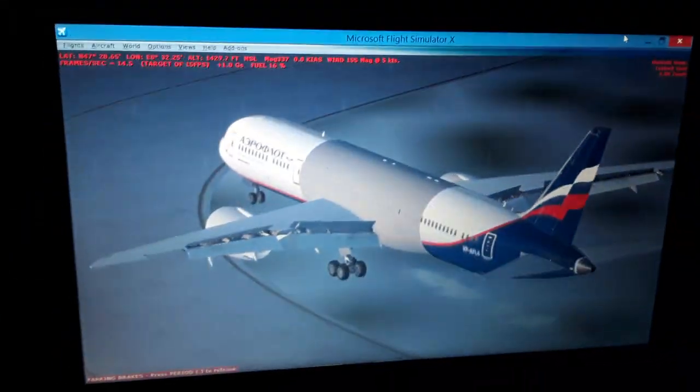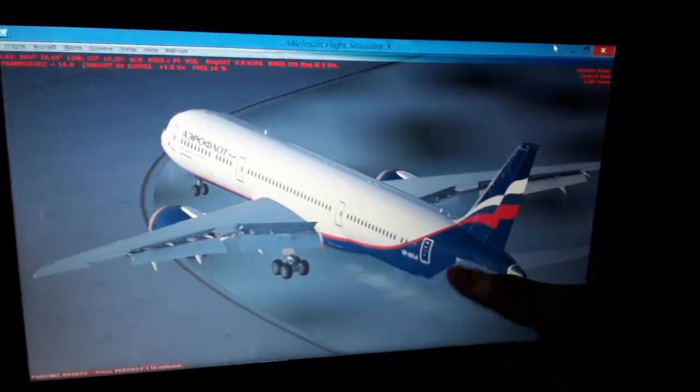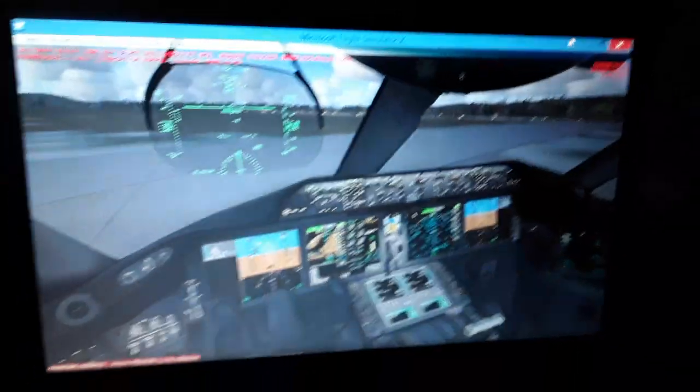It also calculates the mean aerodynamic chord position of the forward wings, which is 23% for this flight. The mean aerodynamic chord of the forward wings is the position where the maximum aerodynamic lift occurs. In the forward wings it is also the position where the stall will begin, when the airflow becomes detached from the top surface of the wings as we fly. So you will see that also. I will show you some of the aerodynamics of the aircraft, the wings, the flight controls, Newton's physics, and the Bernoulli theory of fluids. So I'm going to show you all these things.